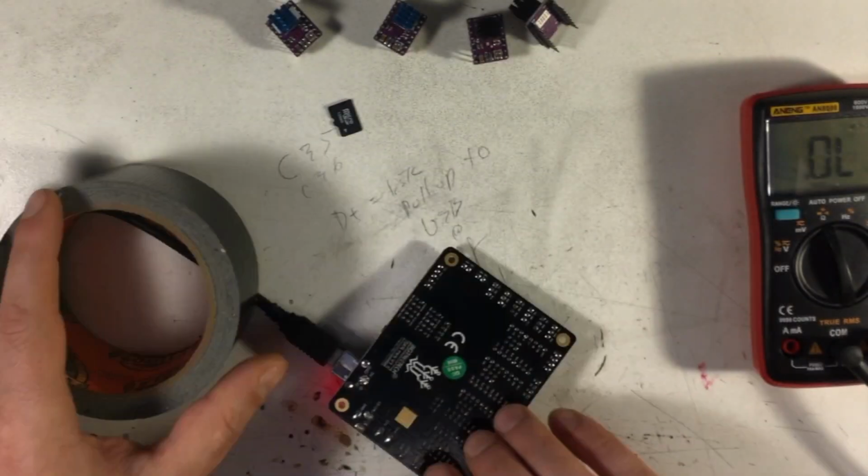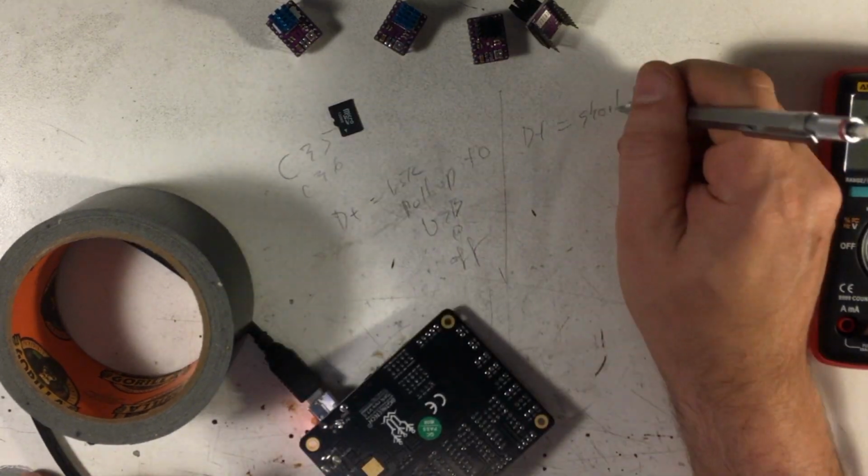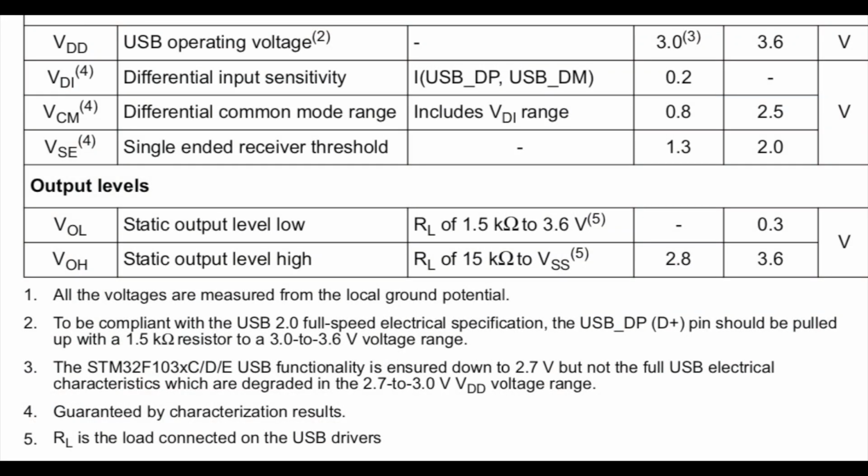So let's try to get an idea about what's going on the other side. So do some power down and power up tests on the USB jack and then some preliminary tracing. We'll make some educated assumptions like we're going to have a 1.5K or thereabouts resistor somewhere on that line.